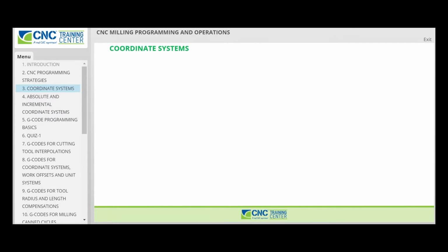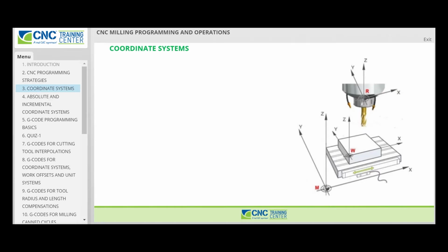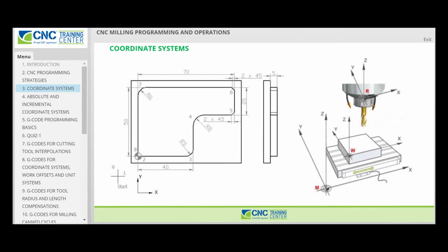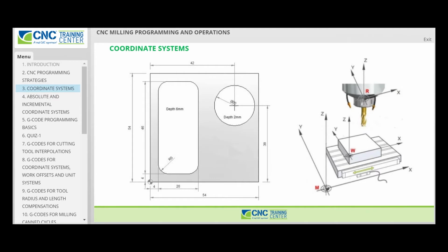When it comes to material removal operations, a cutting tool should be in contact with the workpiece with reference to discrete points that describe both the toolpath trajectory and the cutting geometry. To enable the CNC unit to process toolpath points, a coordinate system should be determined. Therefore, the coordinate system is important for defining the cutting tool's shifts throughout the entire CNC program.